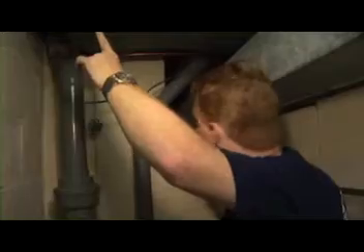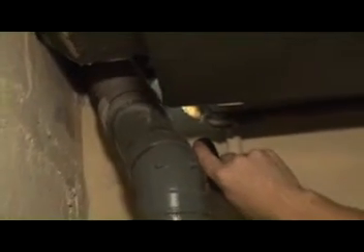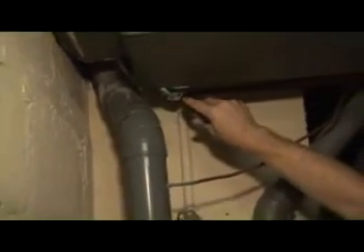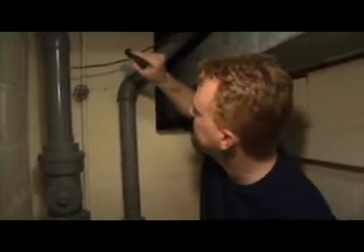Okay, so we've got 3 prime areas of airflow from the basement going up to the rest of the house. First, we have a crawl space here, and I could feel air rushing at me from the crawl space. We have a pipe here. In all likelihood, this is going all the way up through the house into the attic. So not only will we have a hole in the basement floor, we have a hole in the attic floor, and that's a chimney. And that's bringing air up through the house.